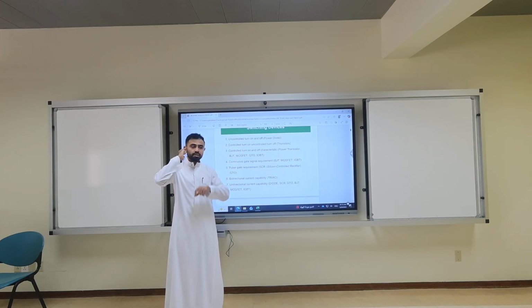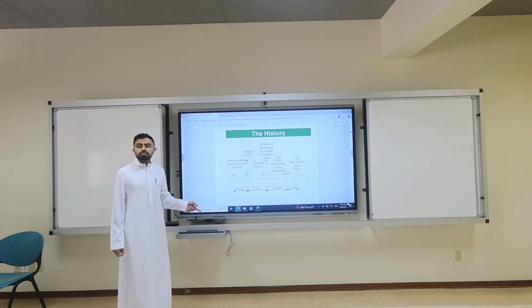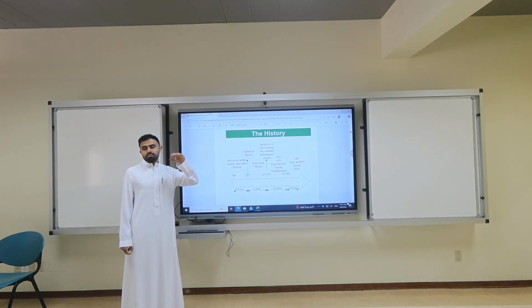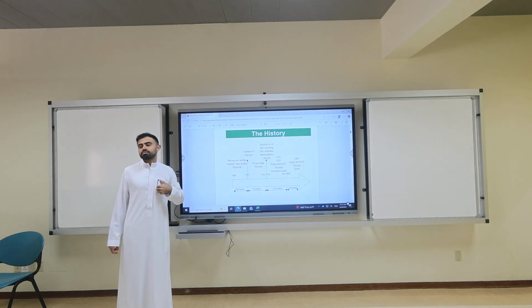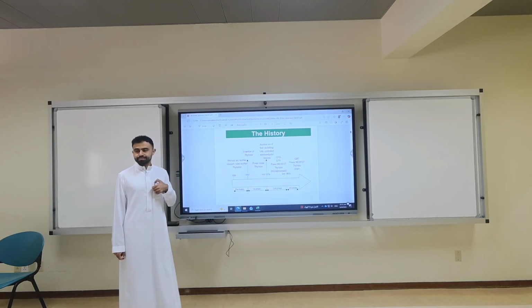It's like two diodes against each other. The Zener diode, I mean? No. The Zener has reverse voltage but clips the DC. The Zener gives you a voltage drop. A triac has no voltage drop, zero. Two parallel, similar to two parallel diodes, plus a gate to control when to turn them on or off.